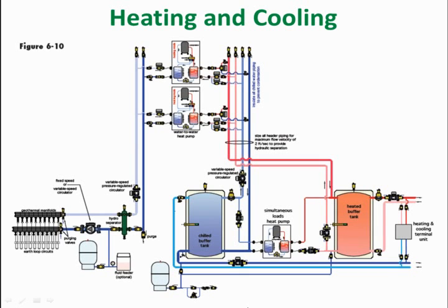So just something to think about when you start introducing hydronic components in the geo systems, think like a hydronic system as far as the components you're going to add. Another thing I don't know that we've talked about here, the center ports of these tanks would be your sensor wells. So whatever sensor, whatever control is driving the system, you've got the ability to put that sensor in a good spot in those tanks by using those center ports.